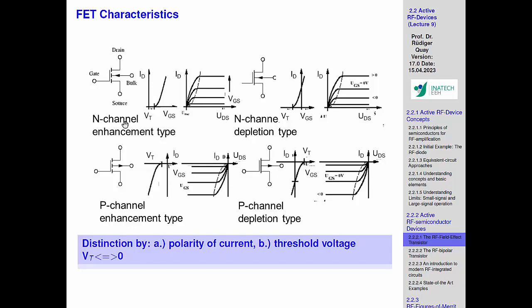There's also something in a MOSFET we talked a little bit about, the carriers and the threshold, and there's two things now. First of all, there's N conduction, which we just talked about. So we had the electrons flowing in the P substrate, but as you know, in complementary MOS, we can also make P transistors, which is a P channel in an N environment.